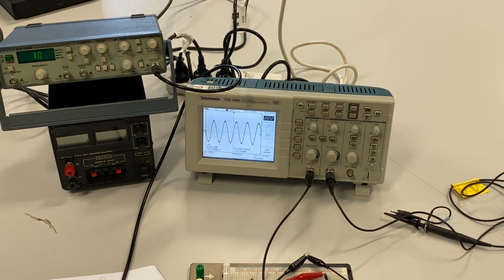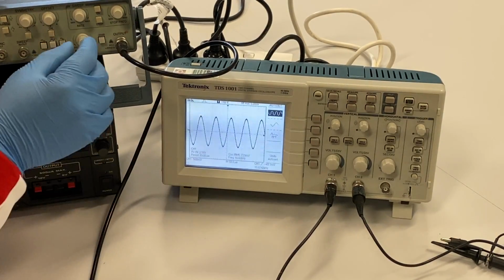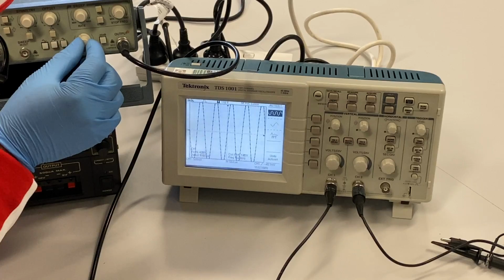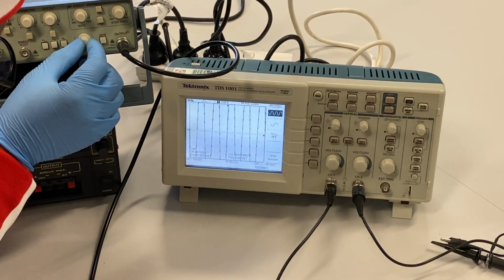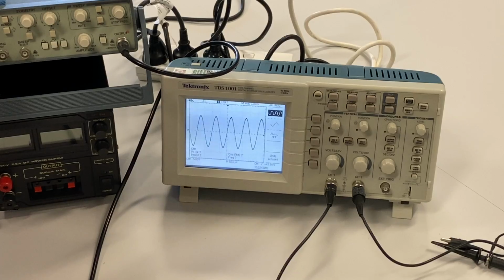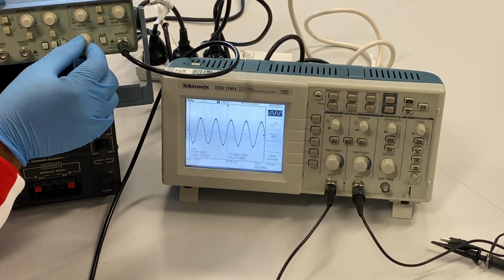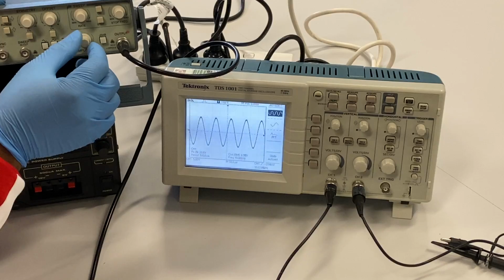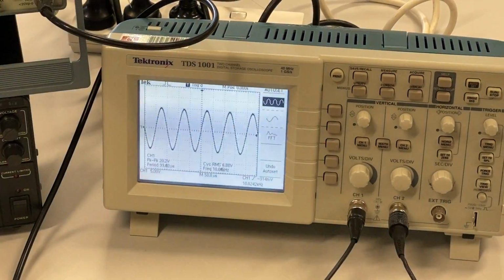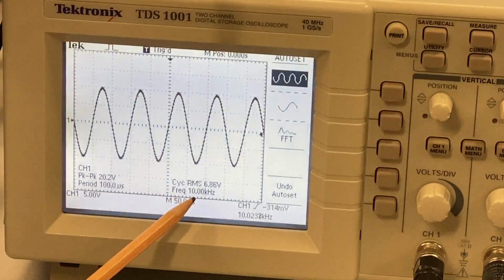So we adjust the voltage knob on our signal generator, from here, right? Let's adjust and we'll be checking the value there. Let's just auto set. Where are we now? 22. Okay, so we're going to go back. 19.9, 20 point... there we go. 20.02 volts, right? Let's check if that's correct. There we go. So we've got our peak-to-peak voltage as 20.02 and our frequency as 10 kilohertz, right?